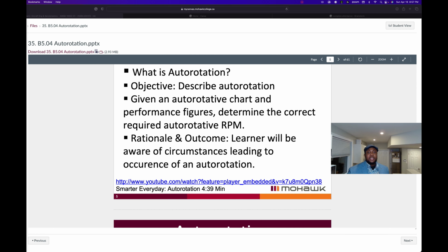If it's not absorbed and we get into ground resonance effect, this could be an indication that this system is not functioning as required, probably weakened or damaged, and may need to be repaired or replaced. So these are your landing gear shock struts. Counteracting ground resonance: vibrations are dampened by both shock struts, and helicopters equipped with wheel landing gear systems will also be able to absorb some of that.